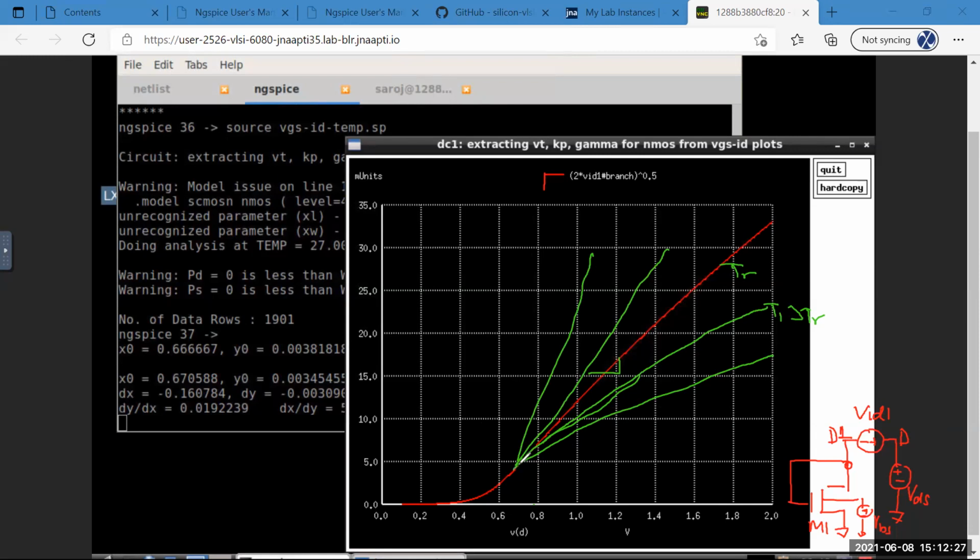For the high temperature ones the current increases, and for the lower temperature ones it will decrease. And there is one point here where there'll be no variation. This is like that sweet spot where if you bias this transistor, it'll magically just remain constant and the current won't vary. So this is what we predicted.